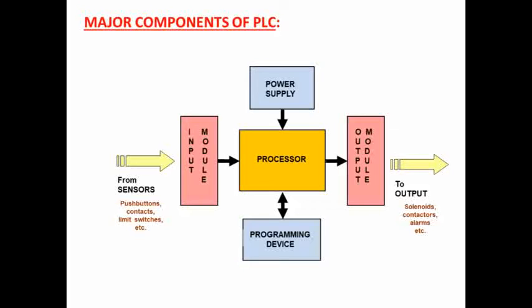These input and output devices, that is I/O modules, which are to be connected to the electrical equipment, are often connected in what is known as sinking or sourcing the circuit. So what is sinking and sourcing? If a solid state device controls the current from the load side, got it? From the load side, then it is called a sinking device. On the other hand, if the solid state device controls the current to the load side, then it is called a sourcing device.